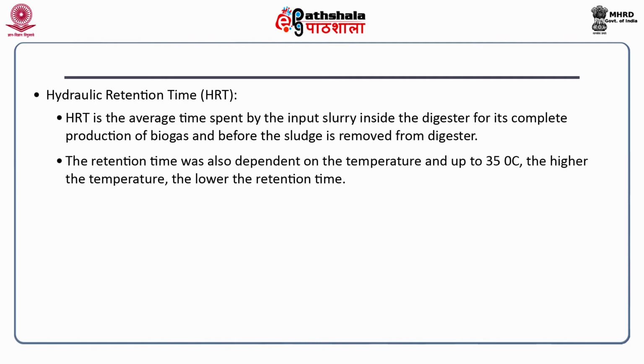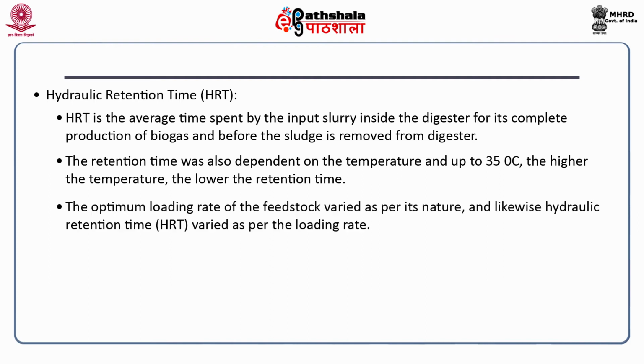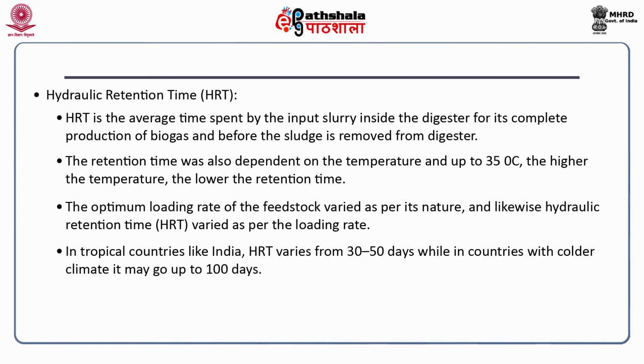The retention time is also dependent on the temperature, and up to 35 degrees Celsius, the higher the temperature, the lower the retention time. The optimum loading rate of the feedstock varies as per its nature, and similarly the HRT varies as per loading rate. So, in tropical countries like India, HRT varies from 30 to 50 days, while in countries with colder climate it goes up to 100 days.